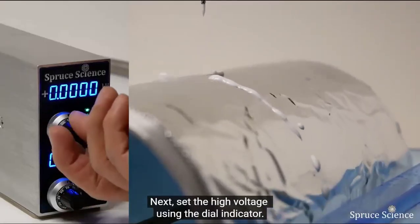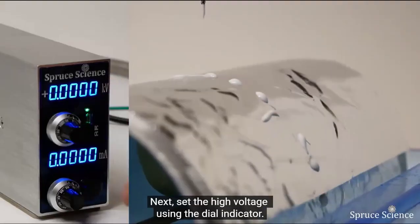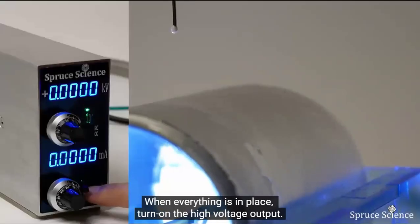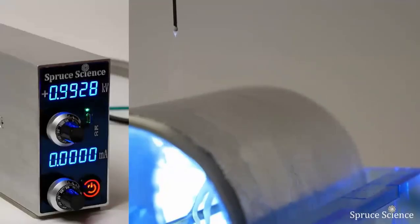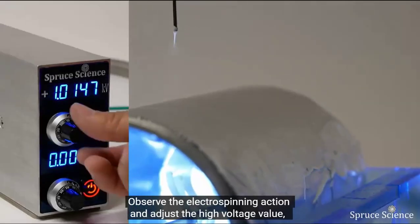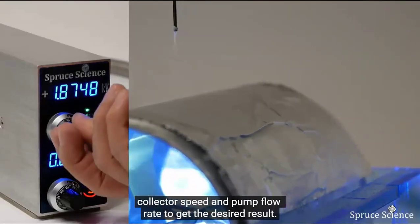Next, set the high voltage using the dial indicator. When everything is in place, now turn on the high voltage output. Observe the electrospinning action and adjust the high voltage value, collector speed, and pump flow rate to get the desired result.